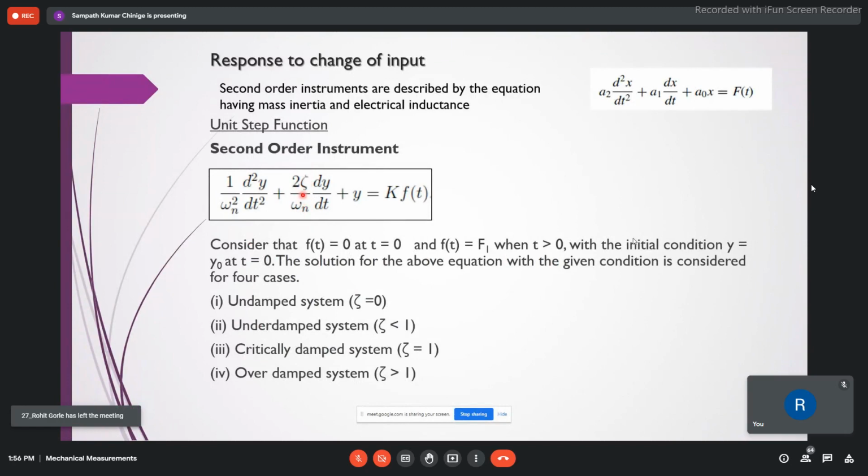Okay, so in the first case, why is a damping system required? Just think you have a needle and a pointer, and there is an input facility. Why do you need a damping system? When there is a vibration, you require a damping system, right? The damping system actually tends to oppose the motion, right? So in order to bring it to an equilibrium position from the oscillation, we generally use a damping system, isn't it?